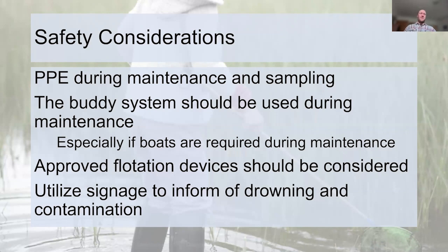Okay, so safety considerations, PPE, always use it. Be sure you protect yourself, especially when you're working with raw sewage, for pathogenic concerns. But also lagoons, it's a big lake, so if you're going out there, wear your life jacket, have a buddy. Make sure you're being safe for whatever kind of maintenance you're doing. Use that PPE.